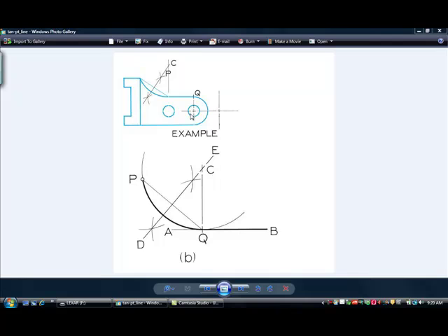One of the important reasons for understanding geometric construction is provided by this example of an arc that has to be tangent to a given line at a specific point and also has to pass through a given point P. In order to demonstrate how to perform this, if you study this illustration, you can see that the point of tangency would be at point Q, and if the arc has to go through point P, we could construct a temporary construction line between Q and P.